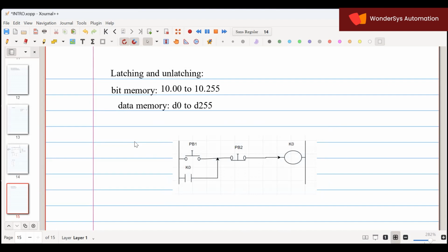So to overcome that, whenever we are using a push button, we know that the outputs are nothing but a storing element. It will be storing a condition of the input, either high or low. Taking that high condition, whatever input switch we are using, we connect a parallel NO contact to it by giving the output address. Now this K0 is storing the previous data. It will not store the present data. It will always be storing the previous data.